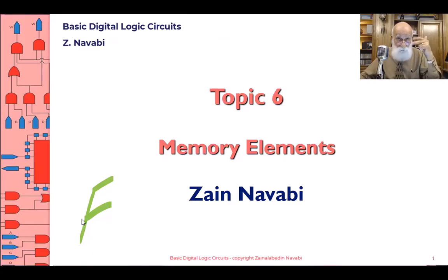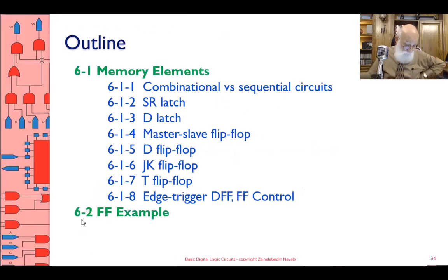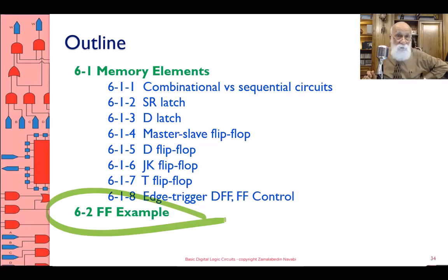So I'm going to do another counter, but to make it different from the previous one, I'm making it a counter that only counts from 0 to 4. That means it is a modulo 5 counter. A modulo 5 counter means that it's a circuit that has 5 different counts. Okay. And then I will start with that and then start adding a few things to it.